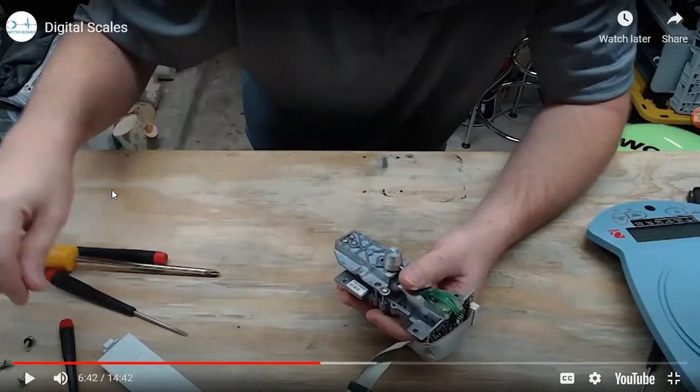You can probably buy an anti-static pad for like $50 or $60. Put the pad there and ground it. That will be the safest way, just in case you have static, so you don't accidentally zap the sensitive components of the device that you work on. It's a good idea to always put the anti-static pad at the workbench. They also have a wrist strap for grounding. So that helps, you can actually ground yourself